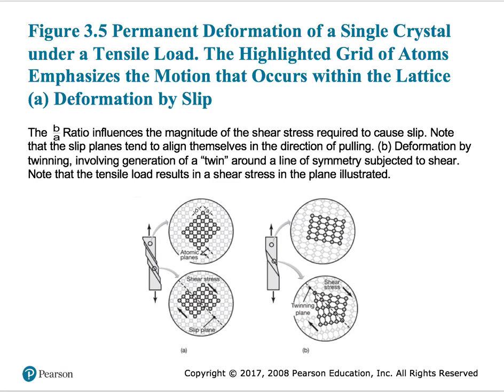It's because, as I said to you, it is similar to moving a carpet. If you have a heavy carpet, how do you move that? You have to create a wrinkle and you move that wrinkle. So if you have a block of atoms, you apply a shear stress on one side, so you create a wrinkle on one portion of that crystal, and then you start moving it slowly, little by little. When that happens, that sample will start moving these atoms along the plane that has the maximum number of